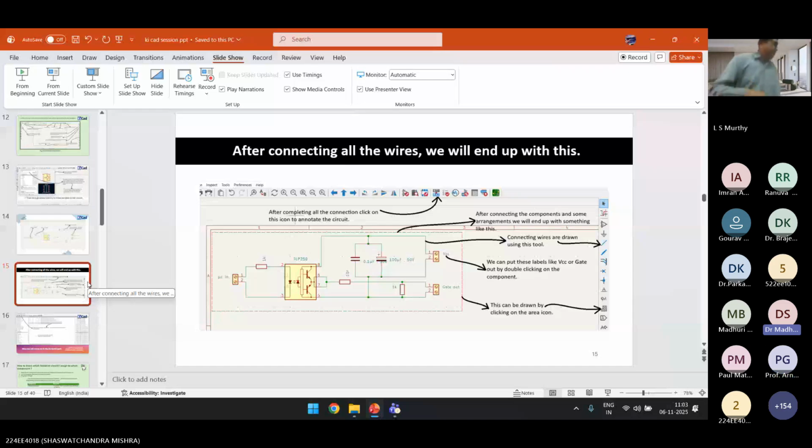Yes. Now you can modulate that according to your need. My question is, when you are switching, is the Arduino at 16 megahertz sufficient? Because your square pulse may not come properly because of propagation delay or gate delay. So in that case, may we convert to some other high-end Arduino, maybe 240 megahertz? I have forgotten the number, but there is an Arduino with a 240 megahertz pulse. So may we use that?